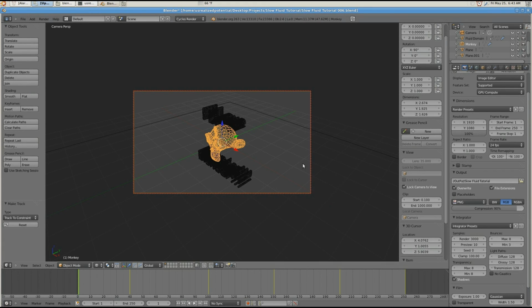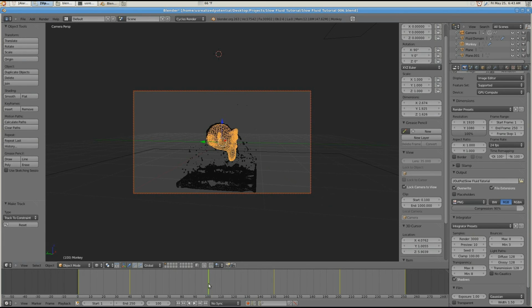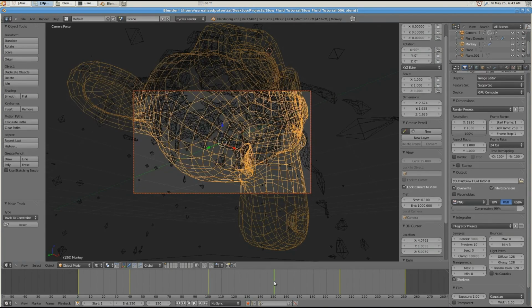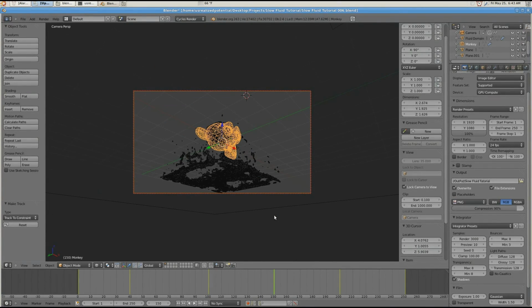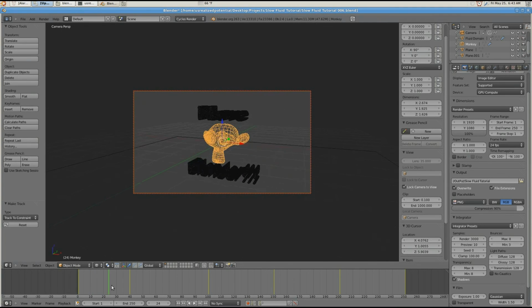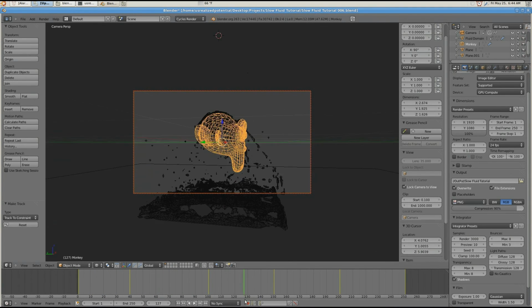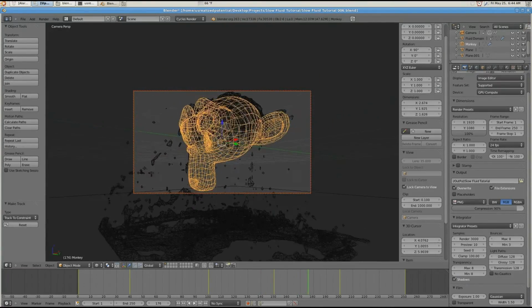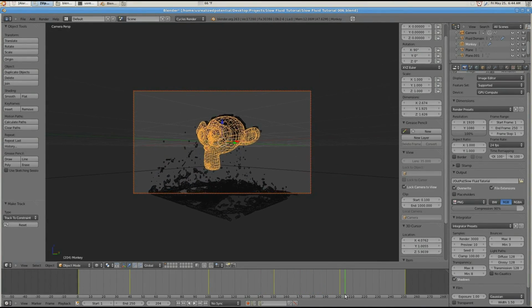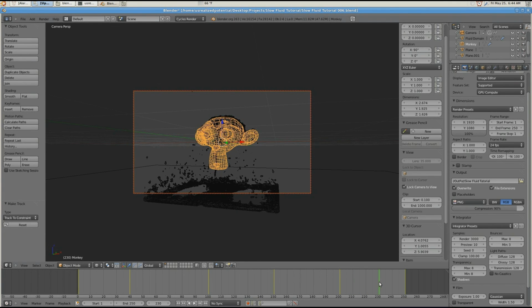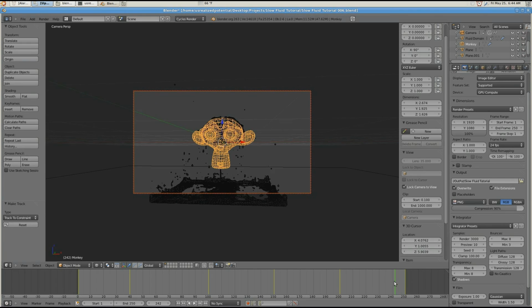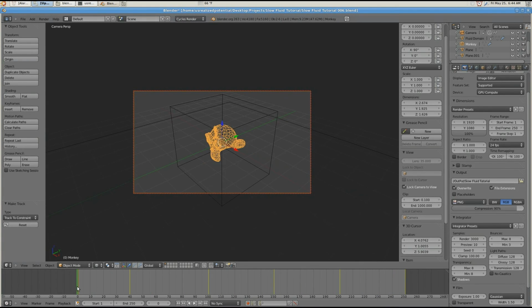Okay, I could probably do more, but I'm not going to play with this forever. I'll just do one test render. Oh, and by the way, the reason I did the track to constraint is just to make sure the camera stays on the target as it's moving. Suzanne will always be centered. Saves you time instead of doing a bunch of keyframes. Just a quick tip.